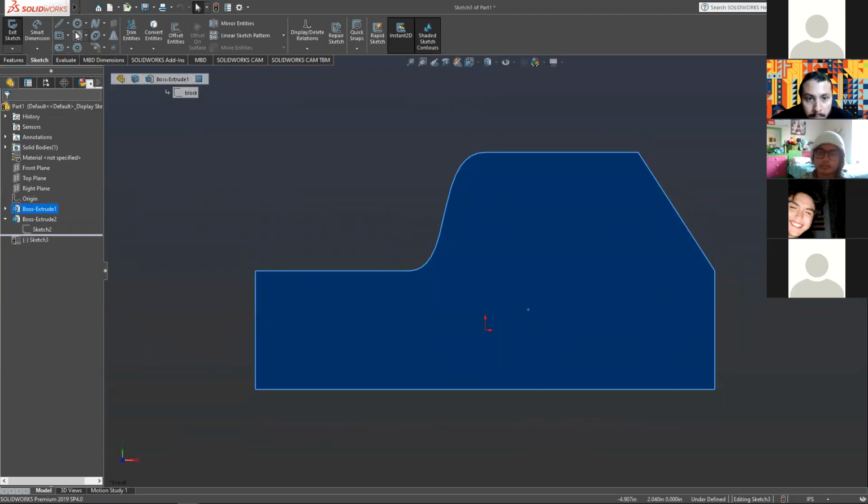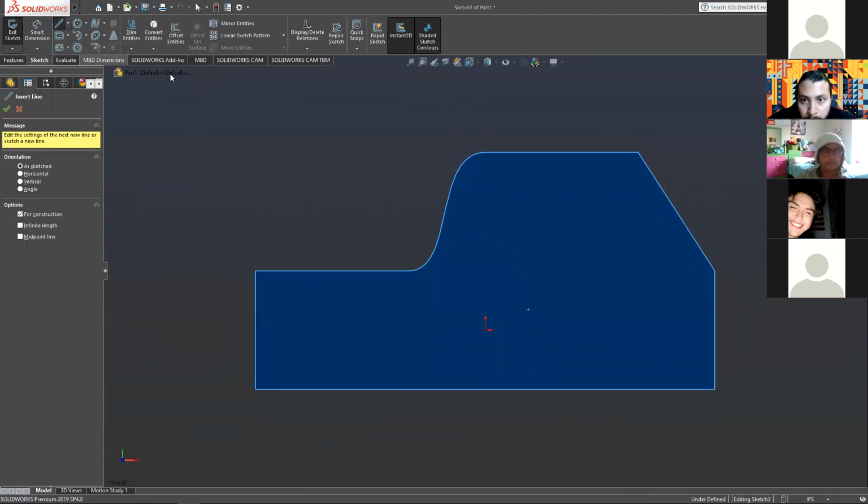So what we're going to do is center line. Sometimes you don't want to go all the way off of an edge just to get to the middle of your part. So if you're in the middle of your part on the origin or some other reference, you can hover over that point and then drop down.